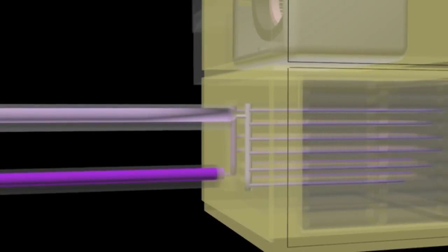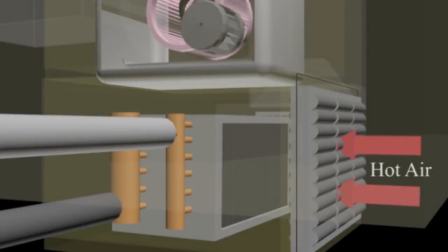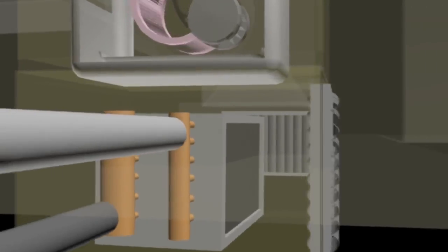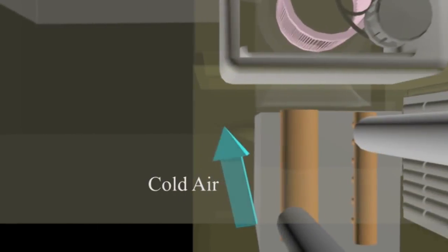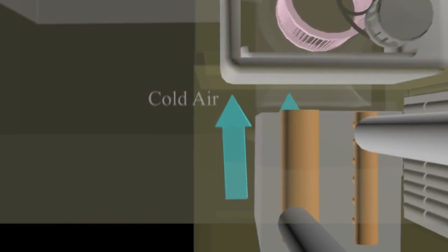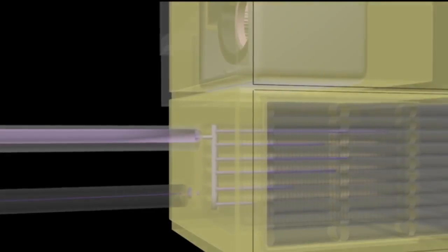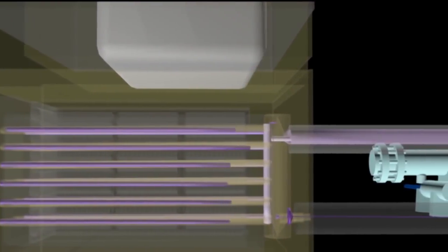In the air handling unit, chilled water will then pass through the cooling coil. In the cooling coil, the hot air goes through and switches to cold air due to the heat transferred to the chilled water. The cooling coil commonly used in this system is the tube and fin type. After absorbing heat from the hot air, the chilled water is known as chilled water return. Normally the chilled water return pipe is colored light blue.